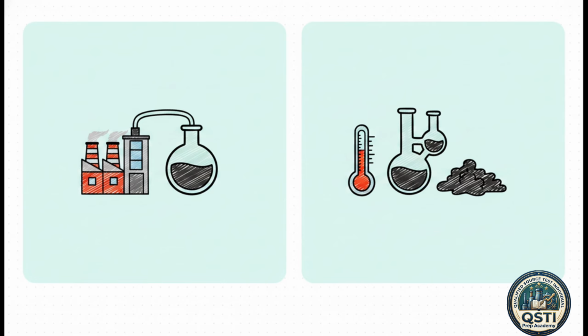While this builds on the foundation of Standard Method 5, the deltas, meaning the exceptions or differences, are what truly matter for accurate asphalt testing. You absolutely need a thorough knowledge of Method 5 to even attempt 5A, but you can't simply swap them out. Method 5A introduces some incredibly strict mandates on heating systems, specific solvent usage, and uniquely designed glassware. This is all to ensure those heavy, unforgiving tar-like particulates don't escape measurement or completely gum up your data.